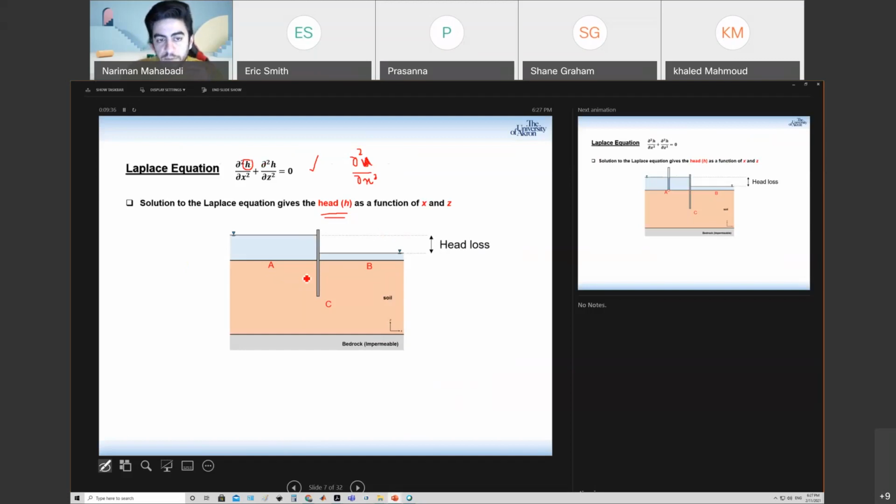There are some specific points for this problem. I have upstream and downstream, and there is an impermeable wall between my two points, right? If I put a piezometer on this special point, it has a known total head, because the level of the piezometer would stand exactly on my upstream. The same thing would happen for my downstream point. These points are exactly located on my downstream. If I put a piezometer, the level would be exactly on the downstream.